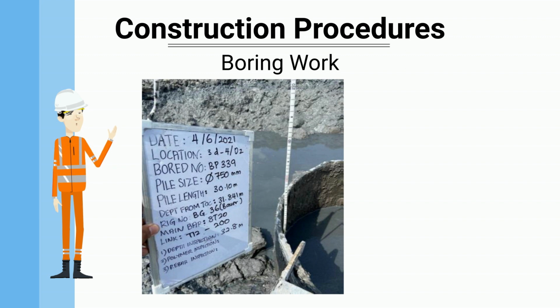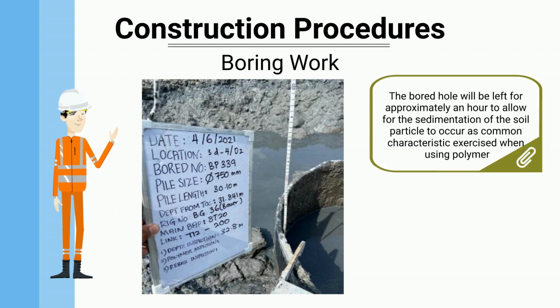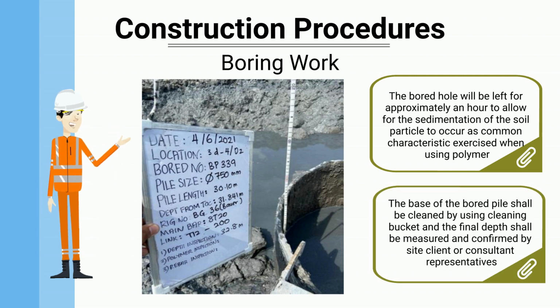Upon completion of the bored pile, request for inspection will be carried out to measure the depth of bored hole with consultant's representative by using measuring tape. The bored hole will be left for approximately an hour to allow for the sedimentation of the soil particle to occur as common characteristic exercised when using polymer. The base of the bored pile shall be cleaned by using cleaning bucket, and the final depth shall be measured, and confirmed by site client or consultant representatives.